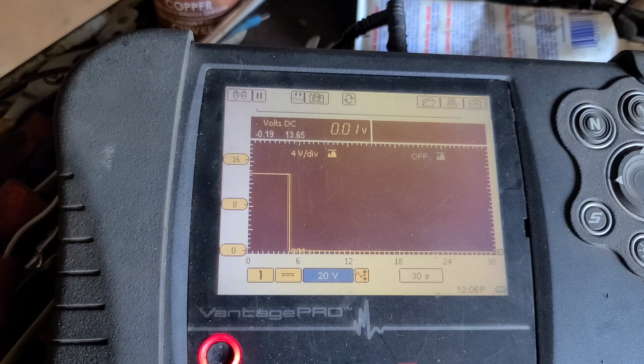So I'm going to check the rest of the wires. I'm going to check the power wire for a voltage drop now. So I've got it on the red wire, which is battery power from feed stud 2, I believe, and the positive jumper wire coming from the battery, and I got 0.01 volts, but I'm going to cycle the key. I got to move my step ladder.